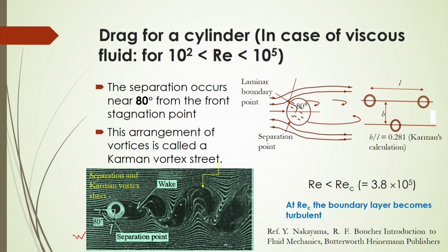So, you will see in this figure how, from behind the cylinder, the flow gets separated at this Reynolds number range, and the vortices will be coming in this way. The flow or vortices, whatever is formed, or the wake, follows a certain wave-like fashion, and this wave arrangement or path arrangement of the wake formation is called the Karman vortex street.